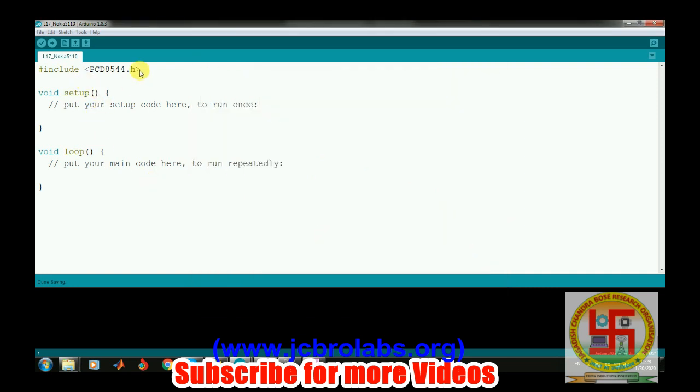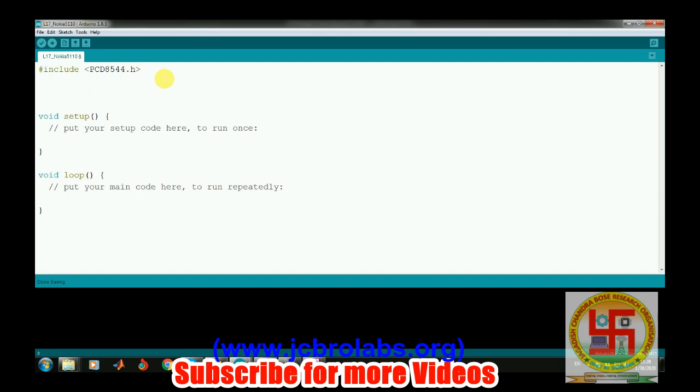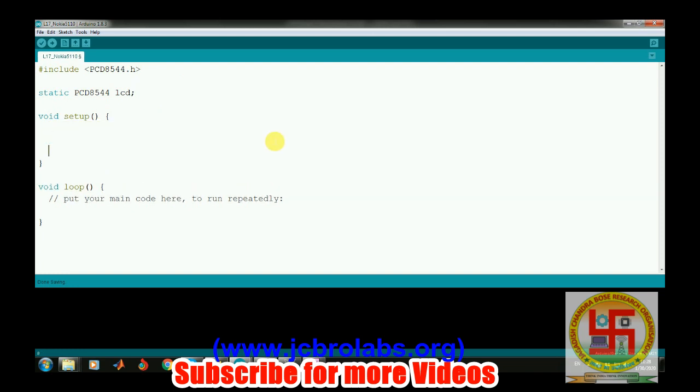So we have already included this header file, and then we have to create an LCD object first. That can be created by making it static, then pcd8544, and we are creating an LCD object of it. Now first of all we have to simply begin: lcd.begin, 84x48.